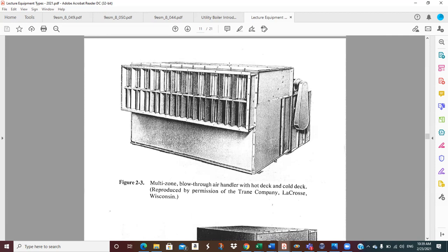And then you see, these are all individual damper sections. And so these little rods up here, when you rotate those back and forth, they will close one of these and open the other. They move in opposite directions. So then you can come in and you can put a supply duct over just one section of this and control the temperature of the air that goes in that supply duct by twisting this rod up on top. And so you put an actuator on that that's in communication with the thermostat.